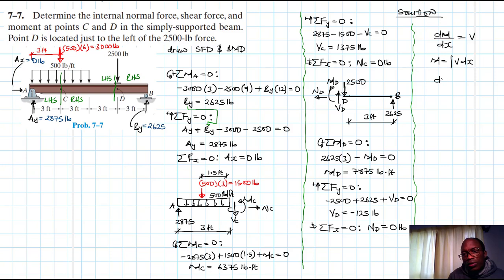And we also know that the rate of change of shear with respect to x is equal to the distributed force, and therefore shear itself is equal to the area under the distributed load diagram. So having these two relationships, or these differential equations, we are going to use them for drawing the shear force and the bending moment diagram.